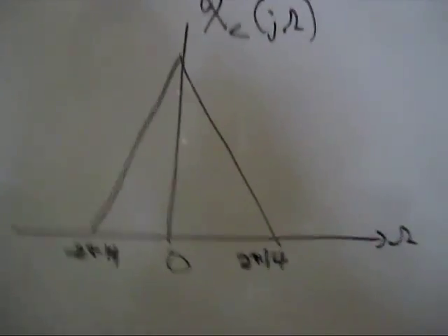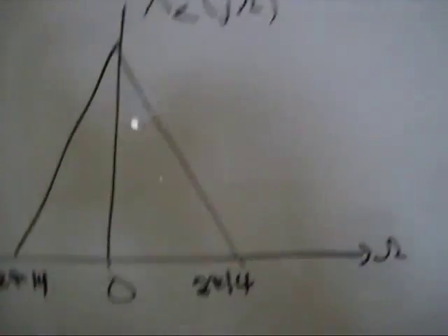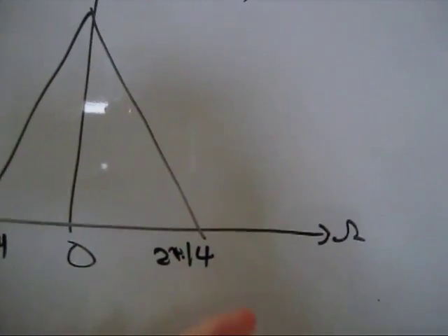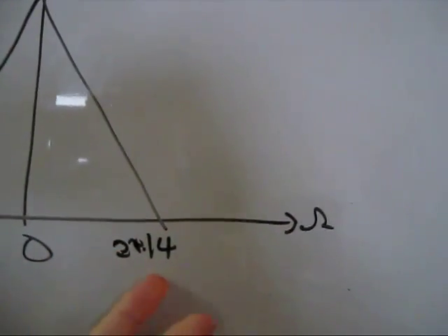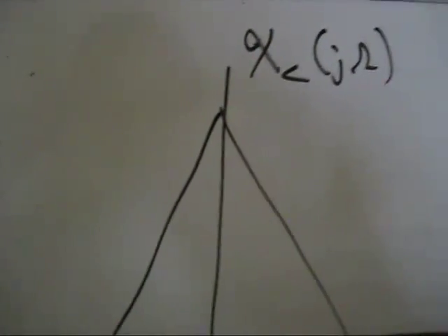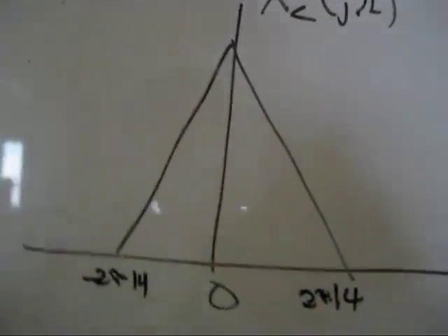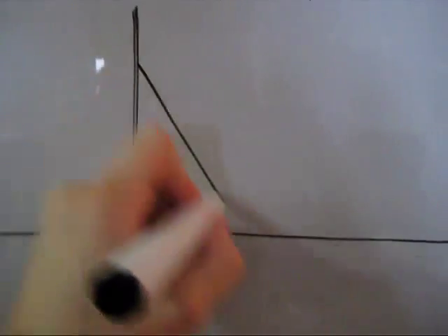All right, so this time we're actually going to have to sample at twice the maximum frequency here. So let's go through that, shall we? If you were to sample that and then take a look at the spectrum of it, you're going to have your main one here.